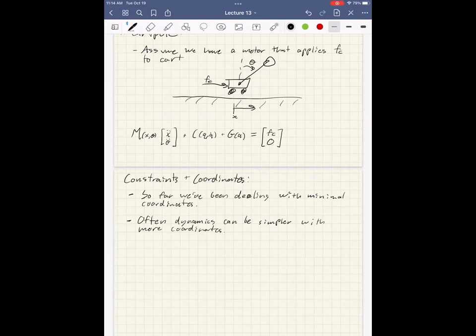I think SE3. Yeah, so Euler angles are a minimal representation of rotations, right? Because there's 3 Euler angles, 3 degrees of freedom, but they have singularities and they're super nonlinear and gross. And pretty much anytime you deal with a real floating base system that has large rotations, you don't want to use Euler angles because they're terrible.